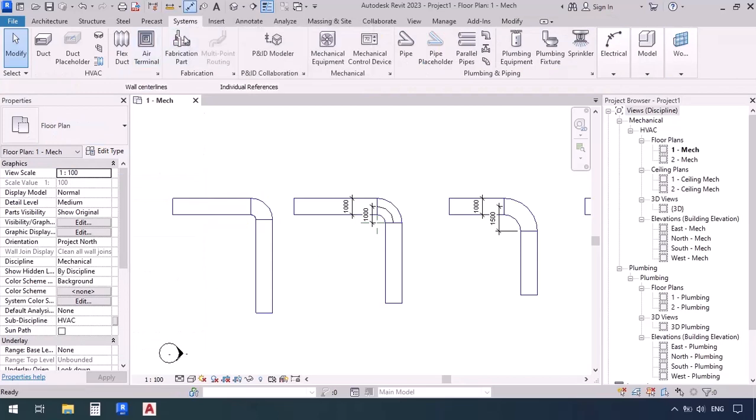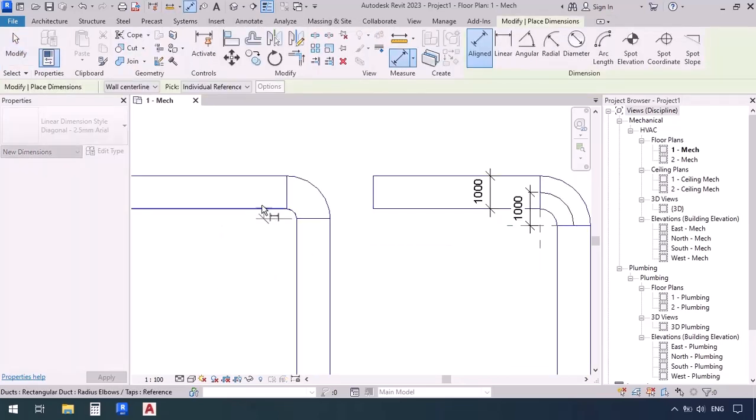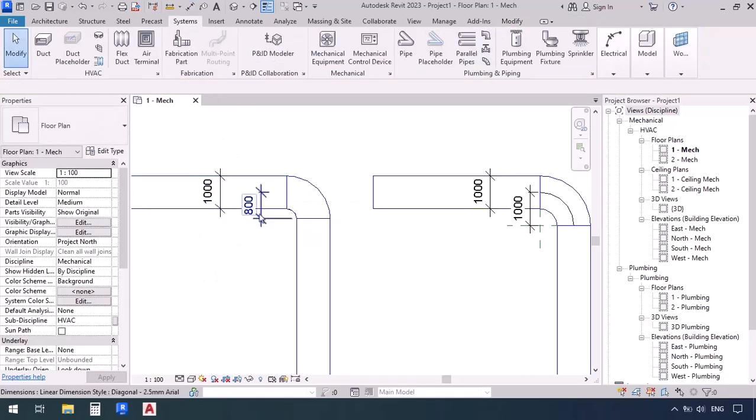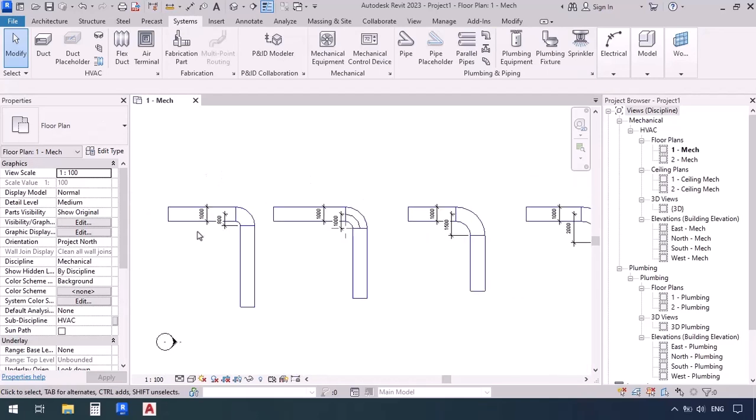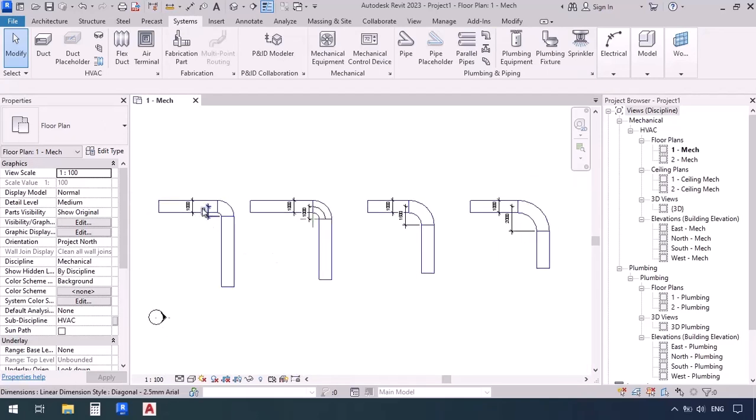Let's measure it to make sure. We go to Align Dimension and from here to the center and blank space and click. Again, first click, second click, blank space, third click. And now it's 0.8. 800 divided by 1000, 0.8. So now you know that you can add any radius that you would like to your project. Depending on your project, you can measure your radius to know what it is and use it in your modeling.